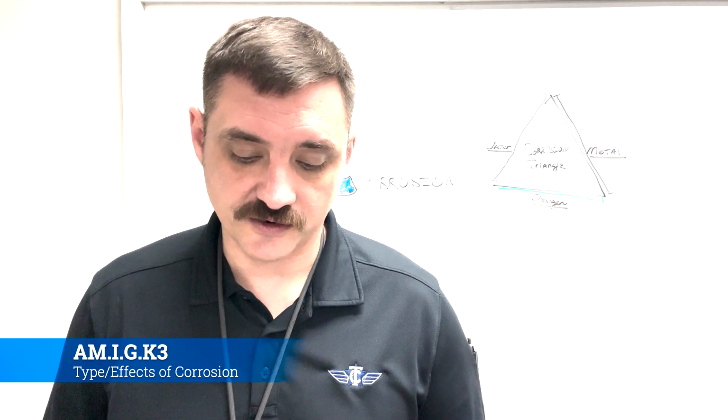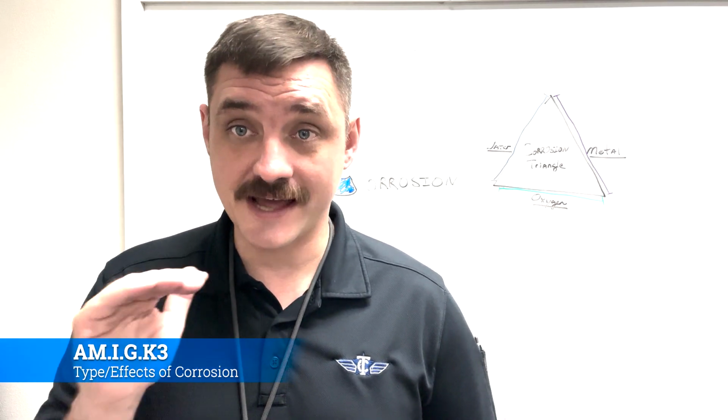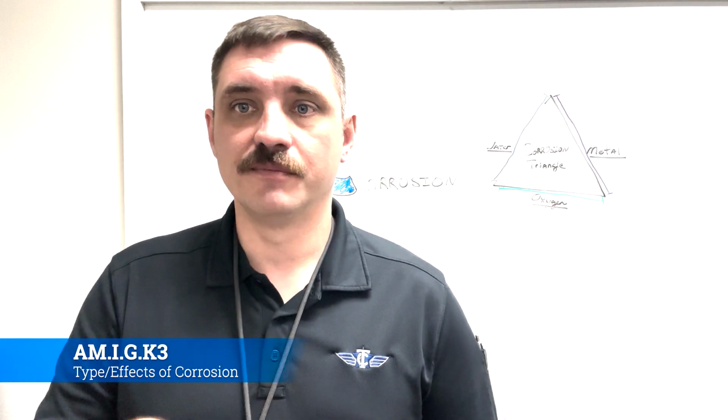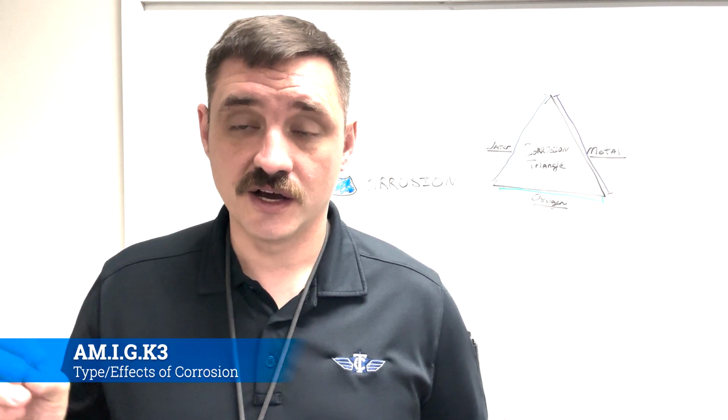Okay, exfoliation corrosion is an advanced form of intergranular corrosion that shows up by lifting the surface grains of the metal by force of expanding corrosion products occurring in the grain boundaries just below the surface. So essentially, this is like a cyst inside the metal. You have intergranular corrosion that's happening, you don't see it, but then all of a sudden it starts to produce.